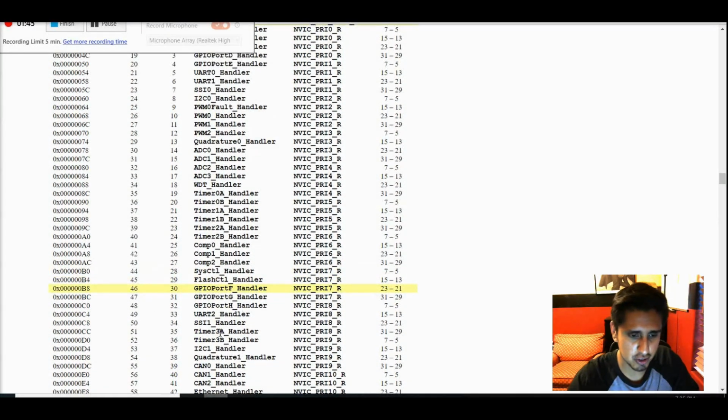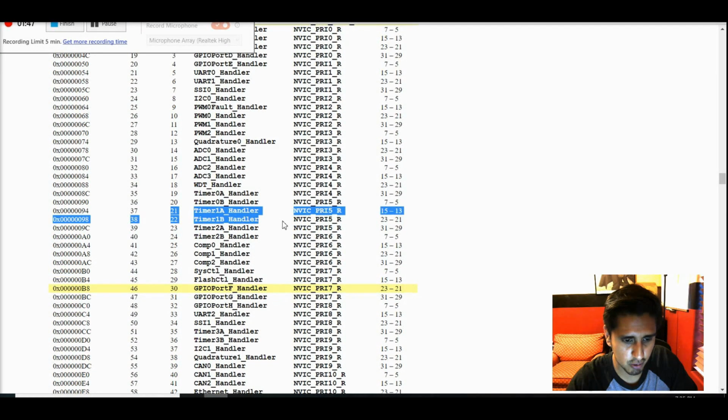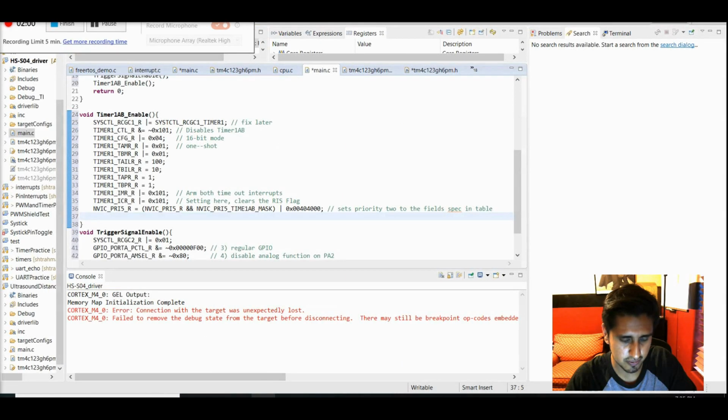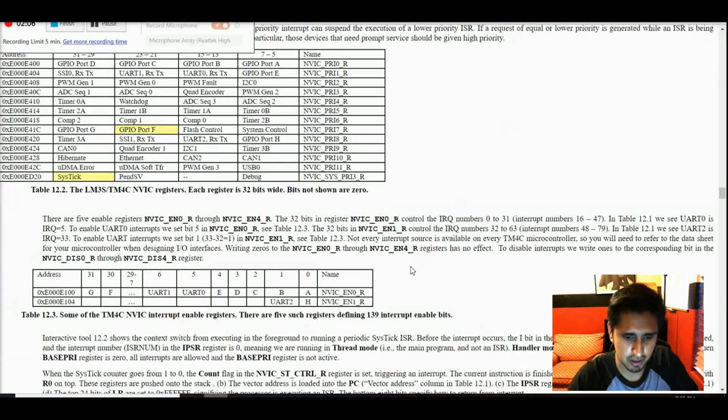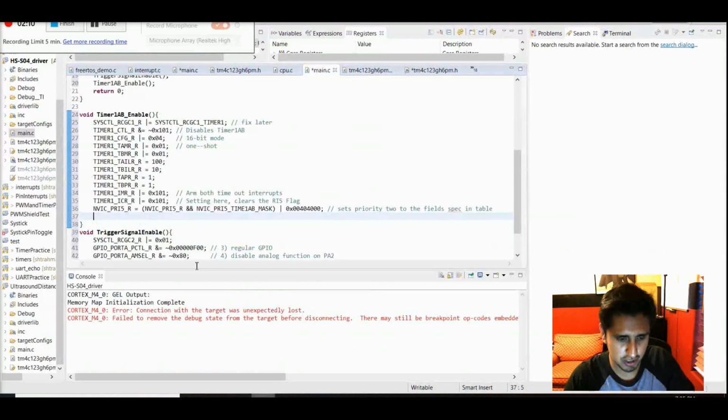And so pretty much we look at timer 1A and 1B, right? We set one bit in field 21 and set the other bit in field 22. And so that'll be what we have to do next. Let me make sure I get the correct name of the register. I'm just going to copy that from here. Control C. Because the value is less than 32, then we know for sure it's going to be in this register.